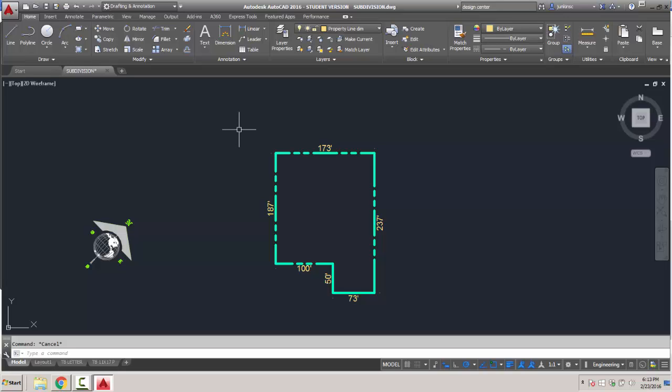If you're going by the book, we're going to set the angle on these things and the elevation. And I don't really think we need those north arrows on there or the angles. What we're going to do now is create our setbacks. And we're going to place some elevations on here also, I think, at some point.